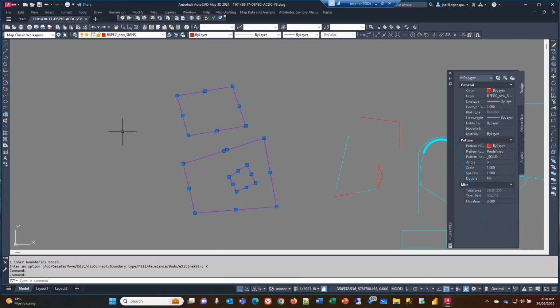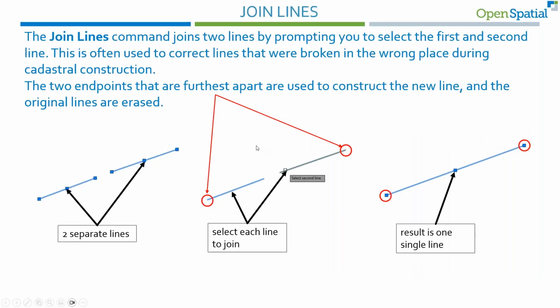Now, normally for presentation purposes, people would have a lightweight polyline and then do a fill in it. And the fill would then look like a multi-polygon, because you can do that. But you cannot take a fill, add attributes to it, and then use that to convert to GIS data. So your hatches don't really work as a data manipulation mechanism. That's where multi-polygons come in quite handy. So yeah, quite an important one there.